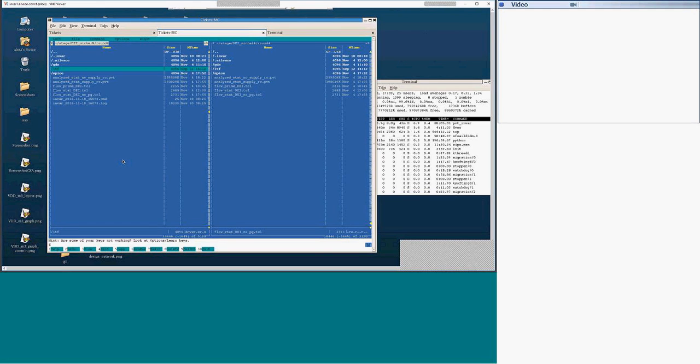Okay. So, yes. This is what I got from Michelle. You can see the screen, right? Yes. This is GDS. For GDS we had to create a layer map, because GDS has no knowledge of layers, layer order, how layers are connected, or what the types of the layers are. These are just layer numbers. For this, I helped Michelle create the layer map based on his input. So we have in this layer map